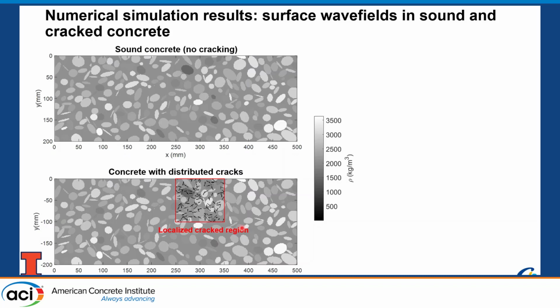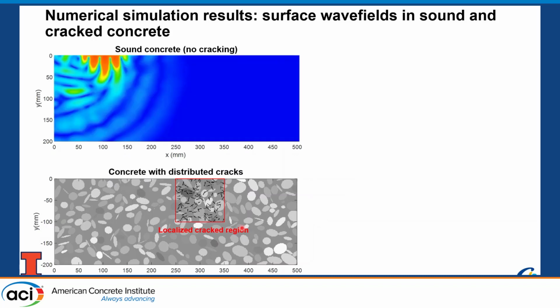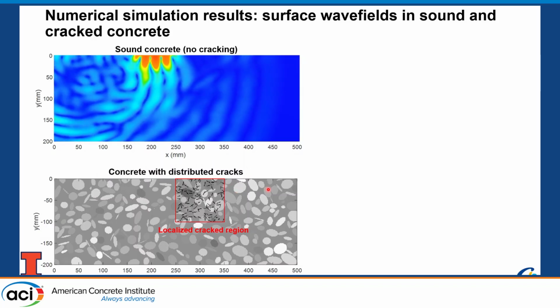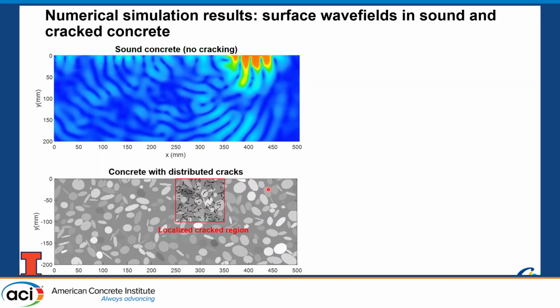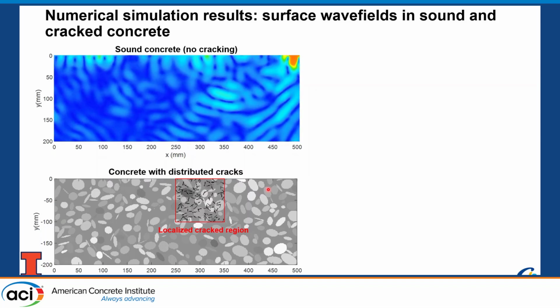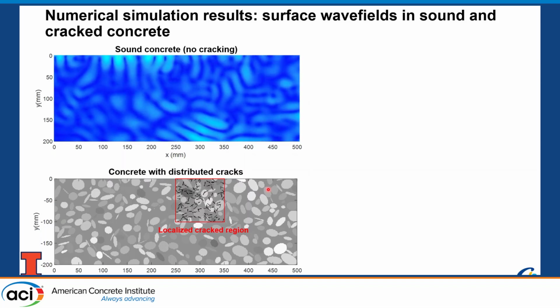At first, we have a surface wave, shown by this colored pulse that shows the energy of the wave. It's going to propagate across, if the animation works. You'll see that the surface wave is a coherent pulse. It's propagating across, losing a little bit of energy, but maintaining its packet. But you also see some waves going backwards, and that's the scatter from the aggregates. That will always happen, and it's disguising everything. This is undamaged material, yet we have all of this scatter from the aggregates.